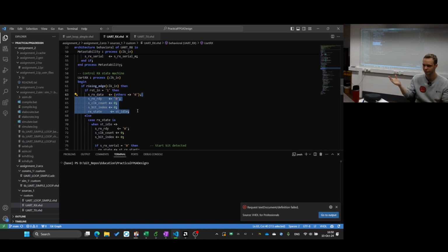But again, this goes into compiler-friendly. We had this in the lecture, compiler-friendly, or synthesis-friendly coding. It means that I do not do these things, because otherwise the compiler, the synthesis or the linter or the implementation has to go through this and recognize all of this. Everything which I remove, which I know I will not use, will make it easier for the tool. Otherwise, the tool has to guess what my intention was. So I will always want to be clear.